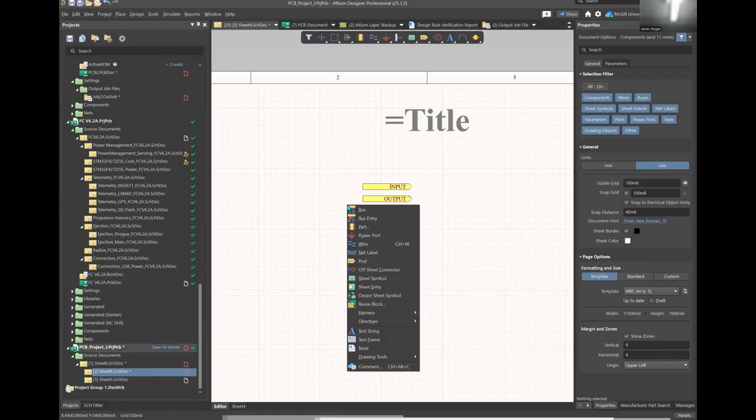What's the port code? When you're placing ports, you should go to one of your lower level sheets. These are all inside the region. Yeah, exactly. While you're placing them, you hit tab. Just do PR, and you can place another one. While you're placing them, you can hit tab and open its properties here, and then you can add a name.